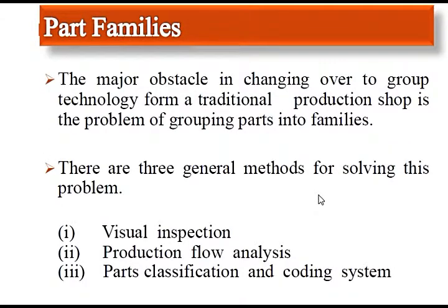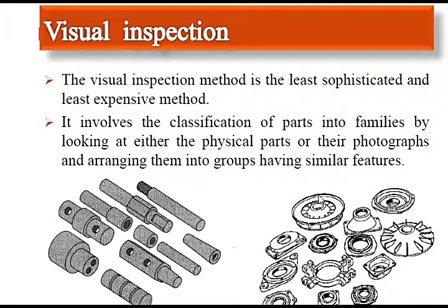Part family. The major obstacle in group technology in a production shop is the problem of grouping parts into families. There are three general methods for solving this problem: visual inspection, production flow analysis, and part classification and coding.